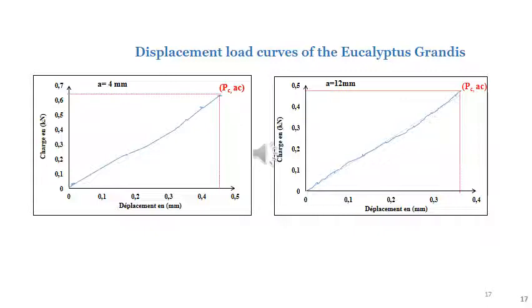The behavior of the specimens during the test can be described as elastic under the action of the applied load. It should be noted that the crack propagates almost linearly until the maximum load is attained. It should also be noted that all the curves recorded show irregularities during loading which can be attributed to several reasons such as wood heterogeneities, internal defects, variability in the growth rings and the sliding of the fibers between them. Cracks tend to propagate in the growth rings corresponding to early wood of low intensity.